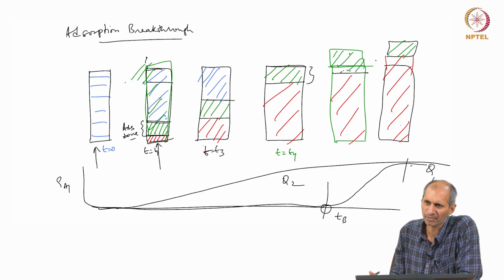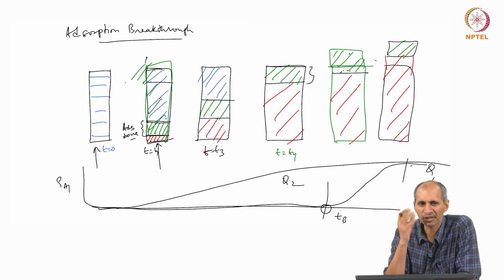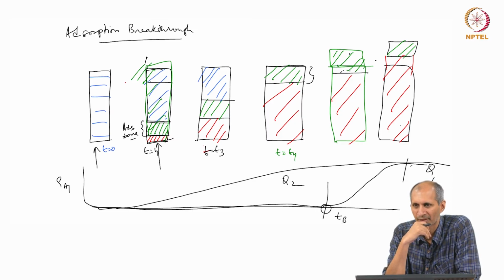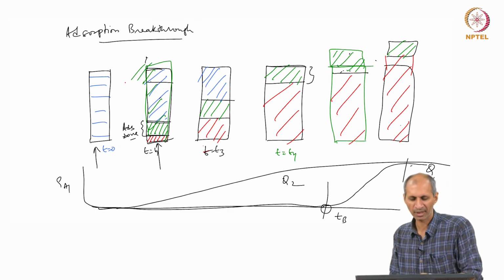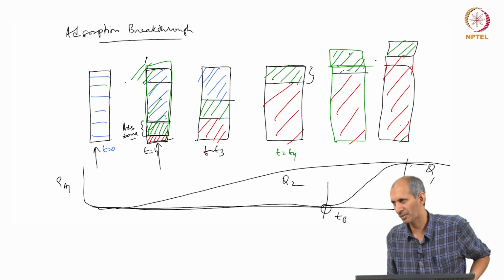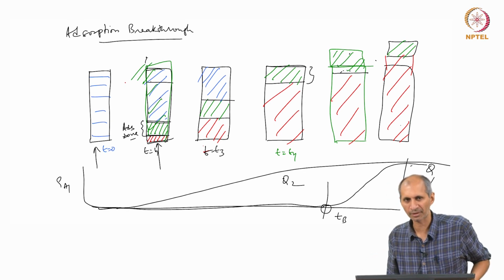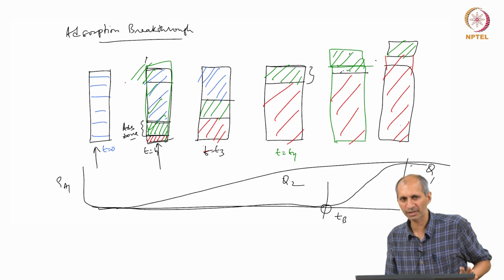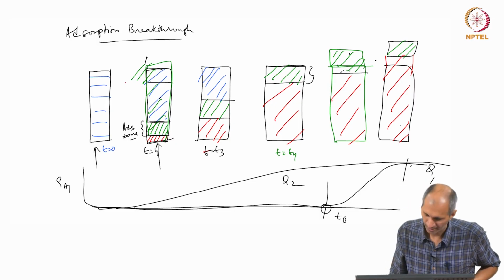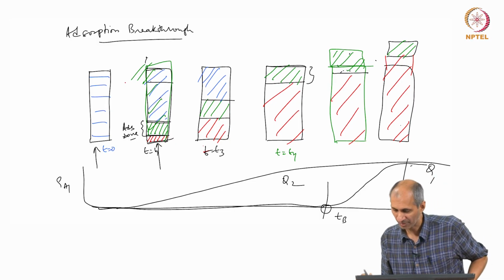This breakthrough curve is important, but for water treatment and all that the flow rates are very small, you can't send it very quickly because pressure drop is very high. But for gas systems usually you are pumping the gas at very high flow rates and this becomes critical. You will lose waste. There the problem is both in terms of managing water quality or air quality as well as the amount that you are spending for adsorbent. So, you are wasting a lot of adsorbent when you are doing this, you are not utilizing the capacity of the adsorbent in this case. So, this is just an aside from that. So, when you look at these, there is a lot of design that goes on into the small tubes that you are doing.